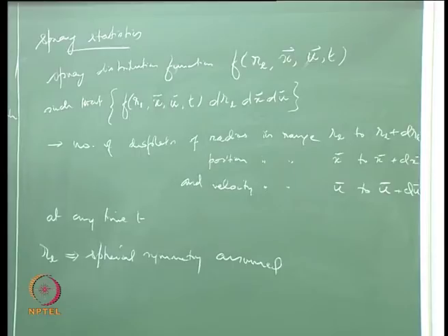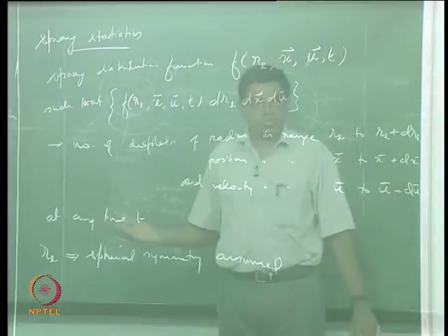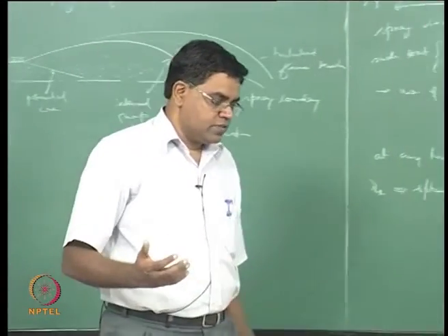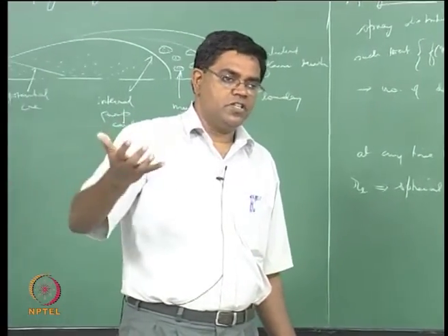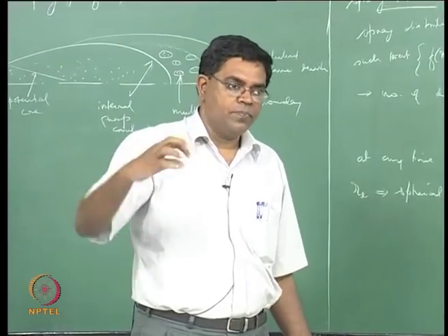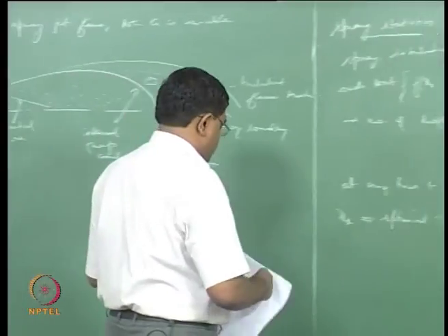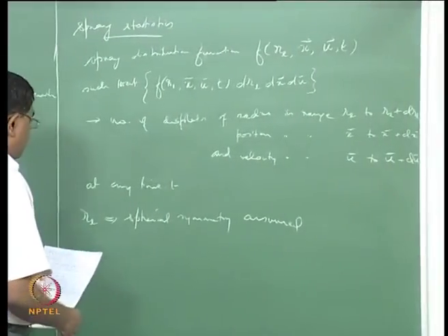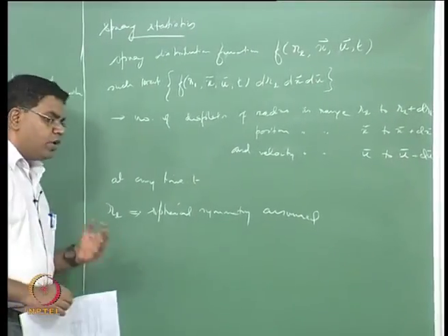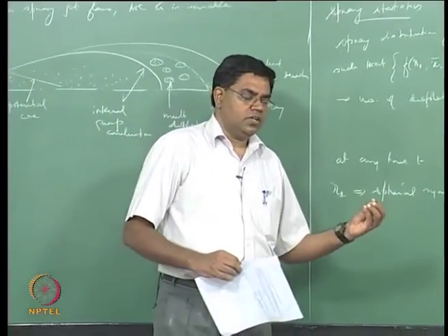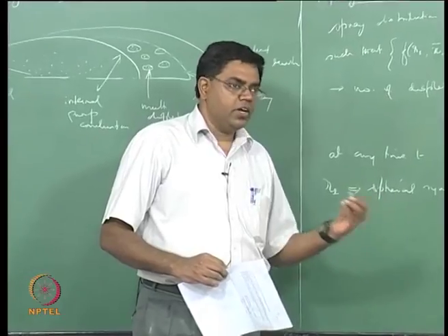Typically small droplets, for example 10 to 100 microns, for most typical fuels have a significant surface tension effect that spheroidizes the droplet. So the sphericity is maintained because of the surface tension. Therefore we have to look at what else is causing the droplet to be non-spherical, competing against the surface tension.